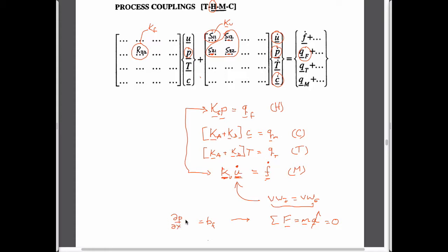If you think about a change in pressure, pressure is in newtons per meter squared. If you look at that pressure change over length, there's another meter term in it just by looking at the dimensions of this. And so it's newtons per volume. So you can think of the body force that we'll end up applying as being related to the pressure gradient.